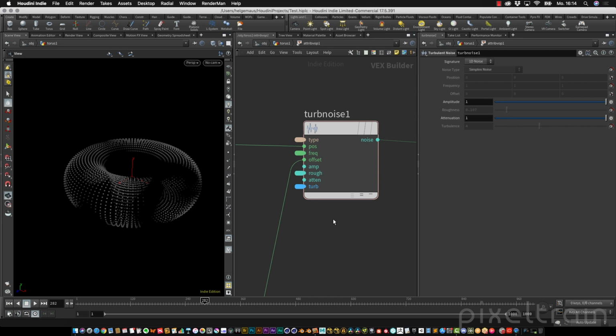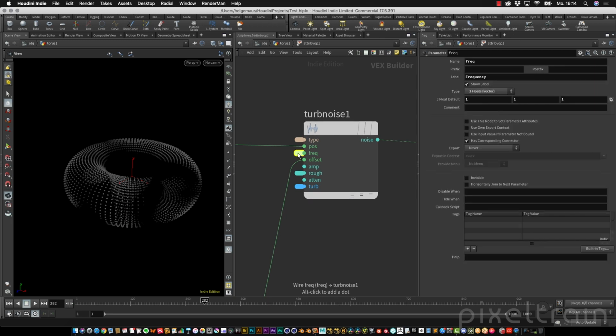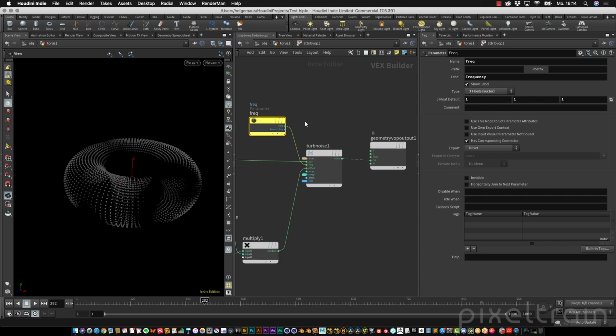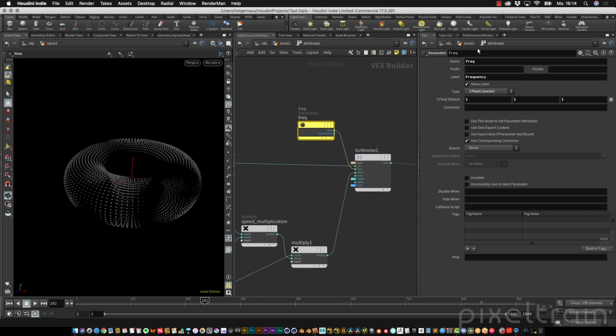And the question really often in my trainings is, what are these flags here for? These flags here are in reality a collapsed parameter node. So if I select, for example, now the frequency here, this little flag you see, it's a parameter node. And we have now all the values filled out from this node here. And if you make a double click on it, you see you can expand it again, so you can change here the names and all these things.